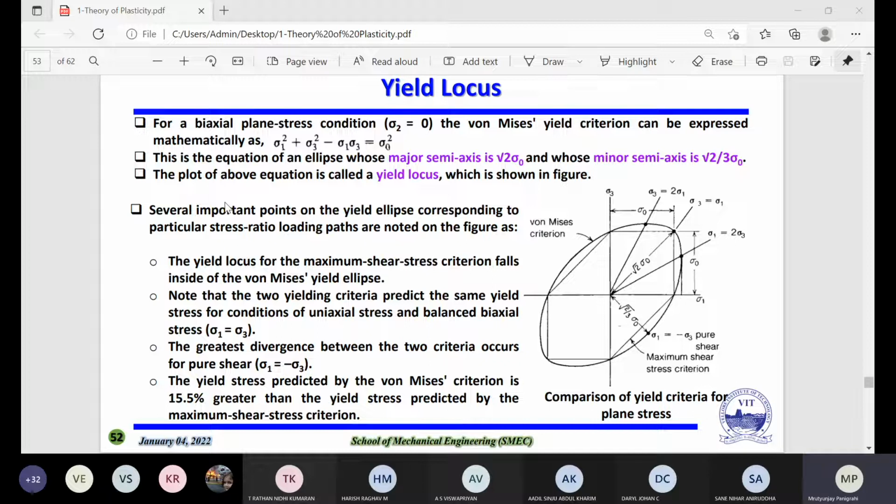Okay, so if you remember, we talked about tau 1 equal to (sigma 1 minus sigma 2) by 2. Similarly, tau 2 and tau 3 also we derived, right? Then we also talked about the deviatoric or reduced component stress. When we talked about the hydrostatic stress, maybe a long time before, we summarized that this is the average of the principal stresses. For example, sigma h equal to (sigma 1 plus sigma 2 plus sigma 3) divided by 3. Okay, this is known as the hydrostatic stress.